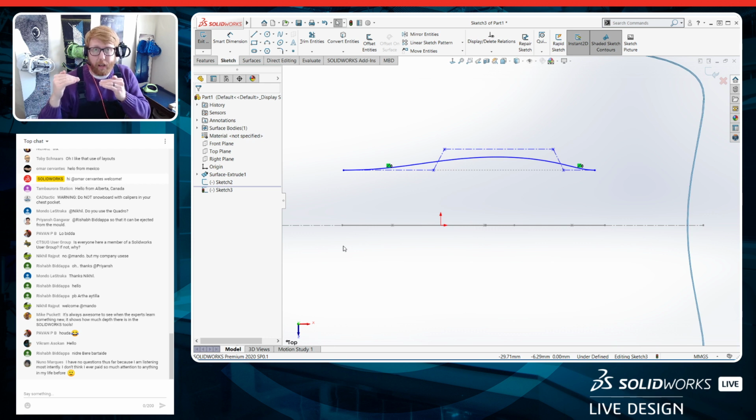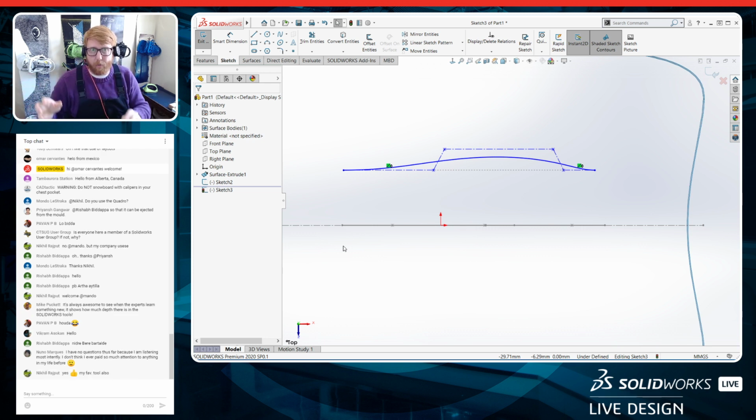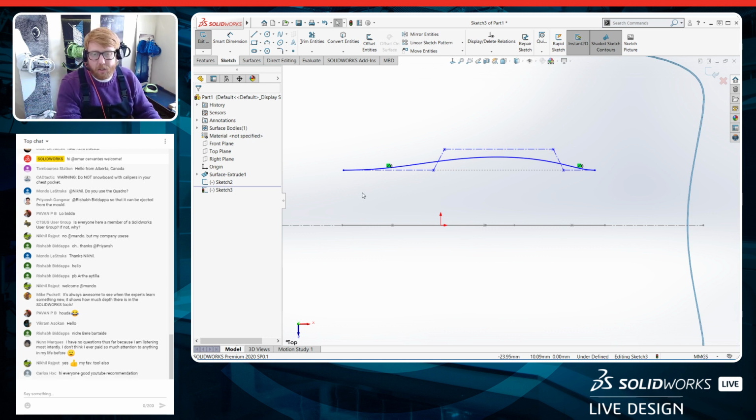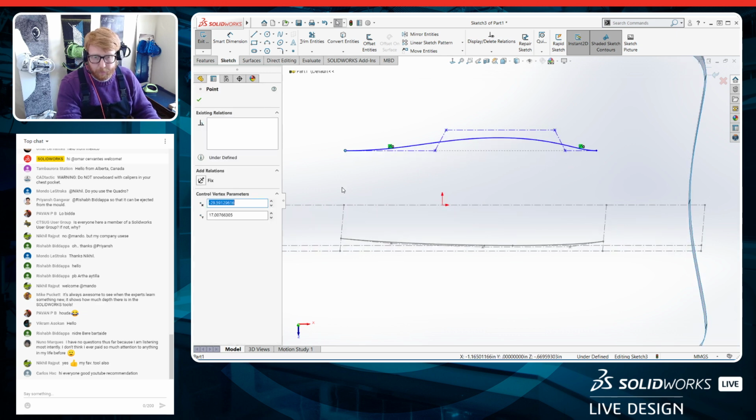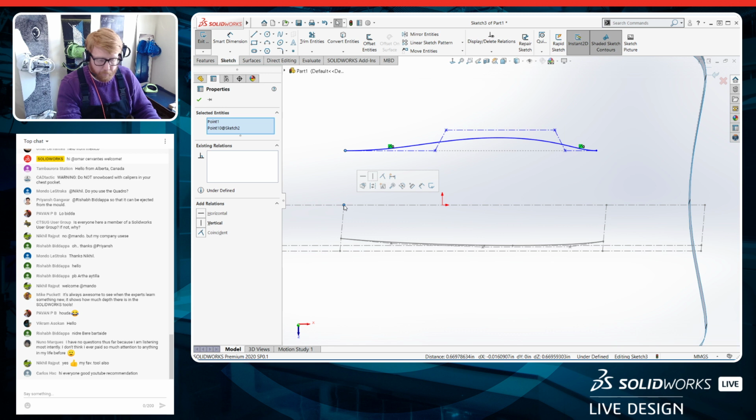to the plane that you're looking at, which is a good thing, because if you had a sketch with 1,000 points in it, you wouldn't want SOLIDWORKS to be trying to grab all those points every time you move your mouse over it. That would be ridiculous, right? So what you've got to do is just rotate the screen a tiny bit, and then you can grab that point.